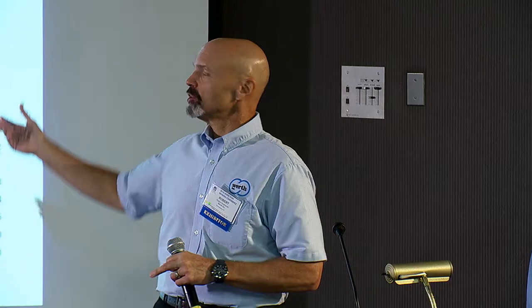But basically, the evaluation of a part is up to you. Wherever you want to do an evaluation of a 2D part over the STL, or the voxel volume. And the voxel volume is nice when you want to fly through it, or you have multi-materials. It's good for things like pins and connectors, or different plastics. So you can actually use the same 2D image, our GD&T software, because it's accredited GD&T software, to do geometric measurements of the part. You can do it either in the voxel volume, or in the STL.